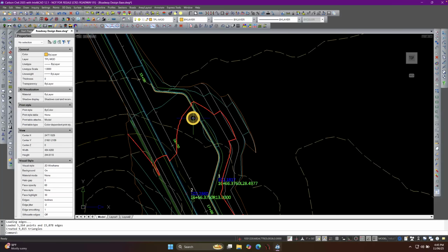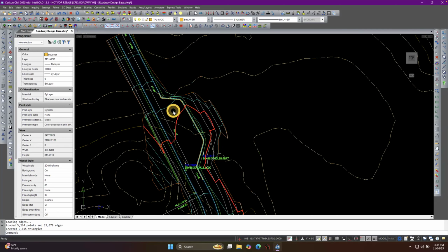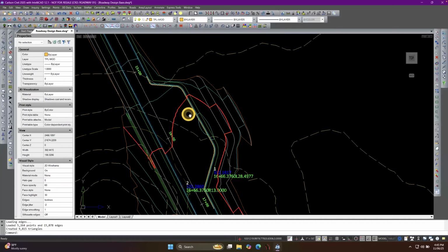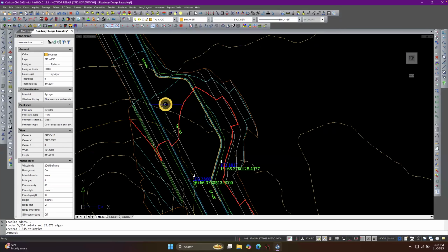So that's just a way that you can adjust these. And a lot of times when you're doing pullovers like that, you would normally not use a profile. You're just going to let it push that lane width out there and stop at that particular location, just push that cross slope on out to that location. Okay, so that's another bit of that adjustment.